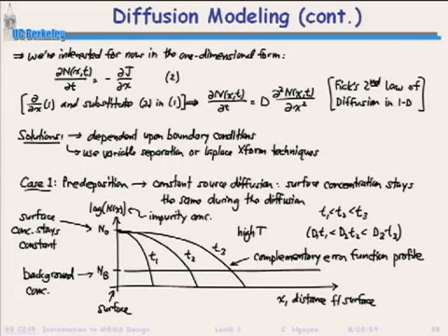Where the diffusion step, again, is taking it up to high temperature and doing that for a certain amount of time. So if I were to plot concentration versus distance versus time here, then initially you'll just have this concentration here, which is not all flat, it's maybe a spike, a delta function of concentration there. But after a time t1 at a high temperature, these dopants move into the silicon, but the concentration at the surface doesn't change because you're continually supplying those dopants to the surface. That's the case we're talking about here.